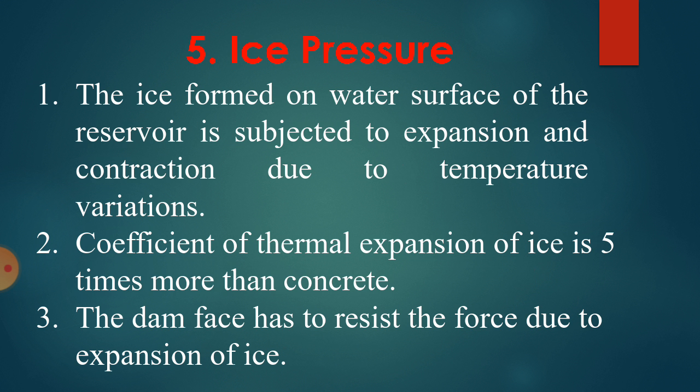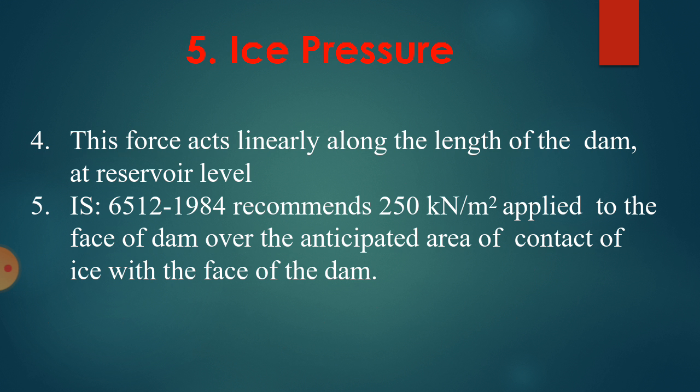The dam face has to resist the force due to the expansion of ice. This force acts linearly along the length of the dam at the reservoir level. IS 6512 1984 recommends 250 kN per square meter applied to the face of the dam over the anticipated area of contact of the ice with the face of the dam.